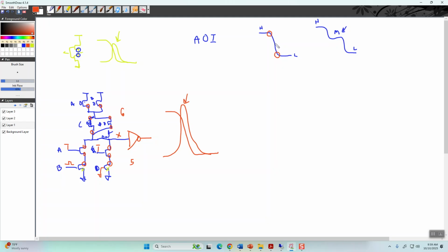And so if you have anything in here and a little bit of noise, it'll get multiplied one way or the other. But you have to pass through -1 twice to get 2. So over here, 1, 2, 3, 4. If you have slope -1, -1, -1, flat, flat, flat, and even maybe not so flat, right? You have now 3 logic levels.